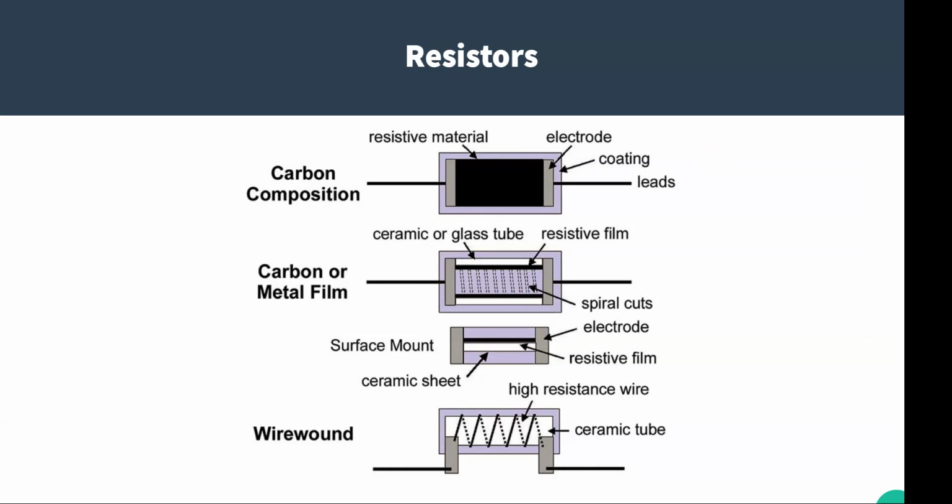You'll see these bigger resistors called wire wound, and it's actually made from a winding of something like nichrome or some high resistance wire to create the resistance and handle a lot of power. You only see those used in DC type stuff or low frequency because of the inductance due to the wire. So it acts like an inductor in addition to a resistor. So they're not very useful at any kind of high frequencies.